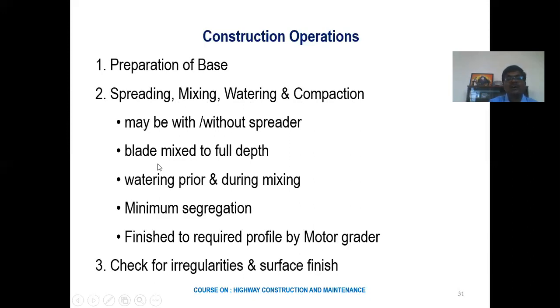For mixing, a blade is used, and before mixing and during mixing, water is to be sprinkled, and we should ensure minimum segregation during mixing of the water and the aggregates. And then the mixed material is finished to the required grade using a motor grader.